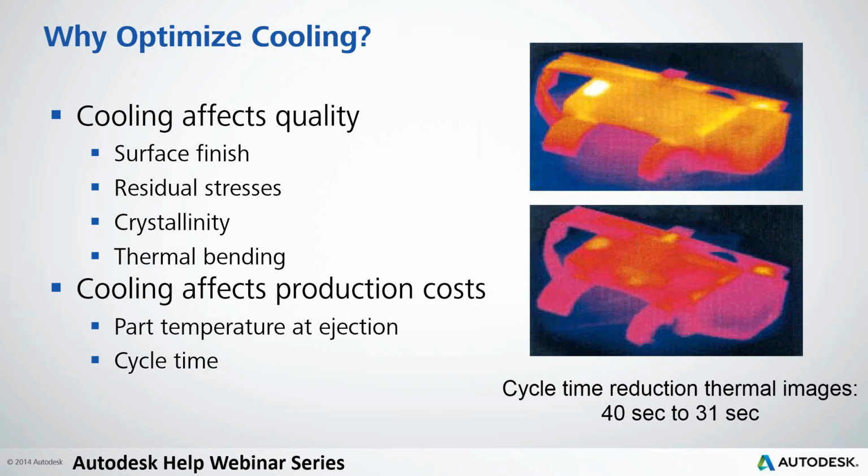If we are dealing with a crystalline part, the crystallinity will not be what is expected. And basically, because of the time that we are keeping the part inside of the tool, we could have some residual stresses and some thermal bending.